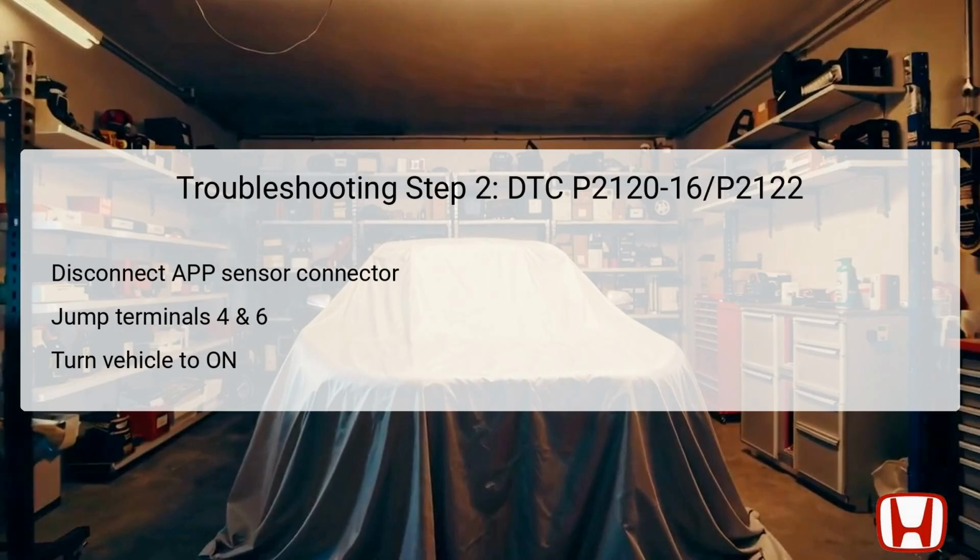The second troubleshooting step involves disconnecting the APP sensor connector, which typically has a 6-pin configuration. This disconnection is essential to isolate the sensor and conduct further tests safely. After disconnection, a jumper wire should be used to bridge terminals 4 and 6 of the APP sensor connector.